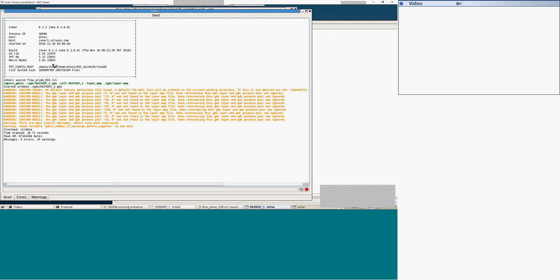This is what you have to pay attention to, that the file system size is adequate and has enough free space to run the tool. In my previous case, I by mistake set it to TMP using some previous runs. And TMP has very little free space left, so that's why I had this problem.